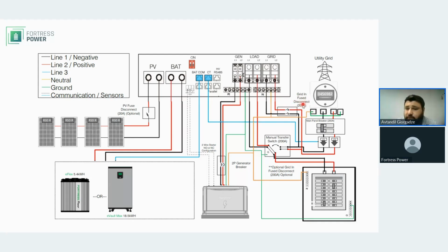So if you try to pull more than 200 amps, it's going to pop the fuses inside. Not both of them are required, really, as long as you have a qualifying overcurrent protection device, which could very well be your fuse disconnect. This could be an optional item, I guess, but with only a fuse disconnect, you could get away with such an installation.